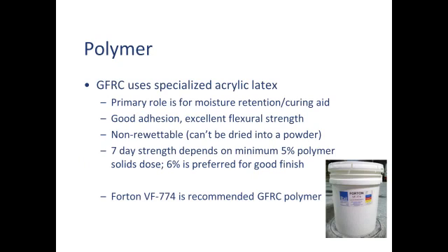GFRC does use a specialized acrylic latex polymer. The main reason it's used is for moisture retention as a curing aid, so that when you're making your GFRC out of Portland cement, because the concrete's very thin, it would normally have a tendency to dry out very quickly. But the polymer helps to retain the moisture so that it achieves a sufficiently high 7-day strength that's basically equivalent to curing that piece of GFRC in a moist environment for 7 days. So it's a curing aid.